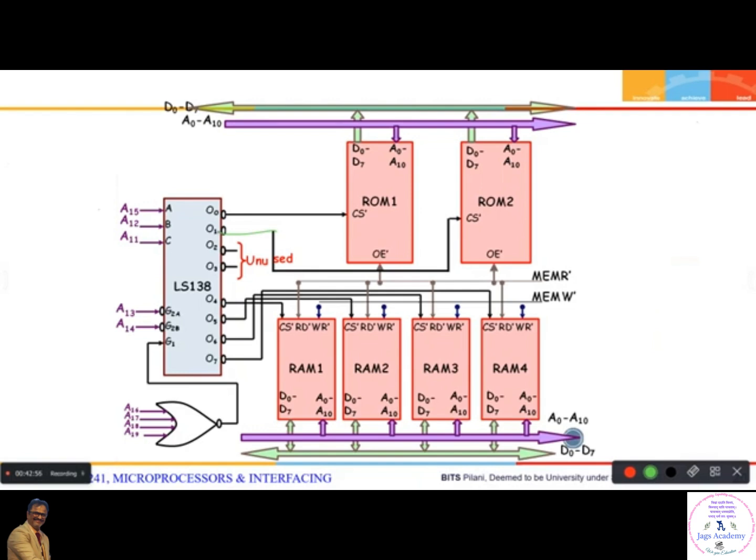Not only the 8086 microprocessor, all subsequent microprocessors which you are using today use this. It may be 1 GB, 2 GB memory based on the microprocessor you have. If you understand this, you can understand all the higher microprocessor designs. And this design is unique for that address map only. Have you understood this? That's very important. This design is for that address map only, which is given as a specification in the problem.